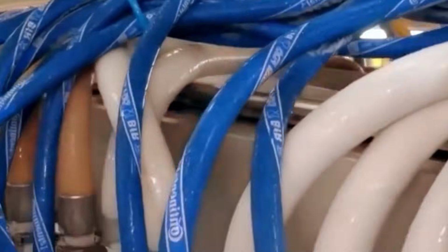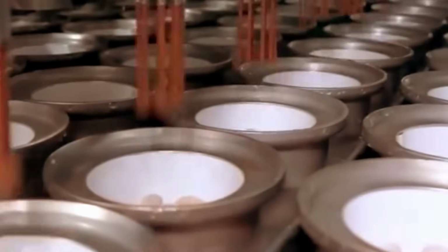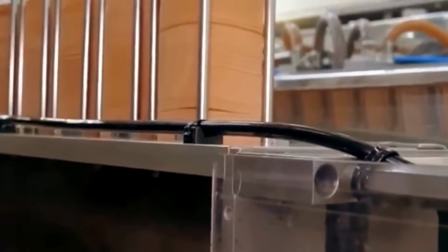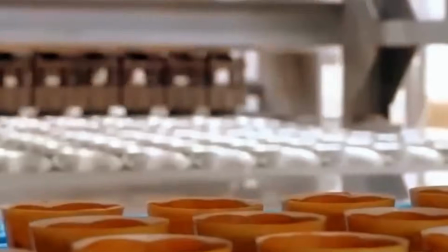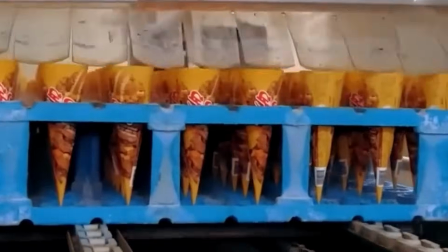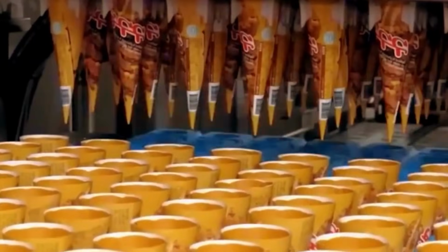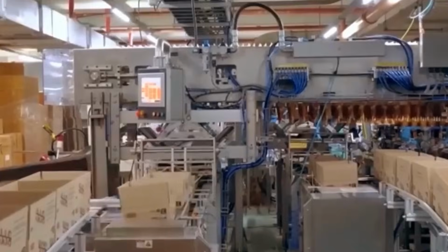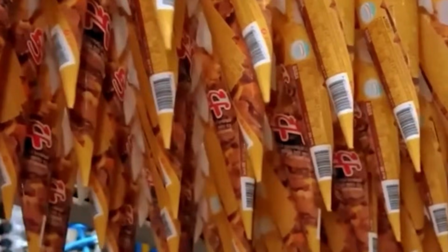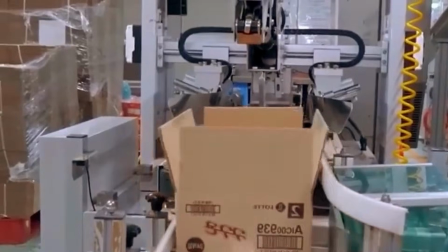Stabilizers and emulsifiers such as guar gum, mono and diglycerides, or carrageenan are added in precise quantities, using dry ingredient feeders with load cell controlled hoppers. All components are blended in high capacity, jacketed stainless steel mix tanks equipped with high shear agitation. Mixing durations and shear rates are pre-programmed and adjusted based on batch size and viscosity targets.